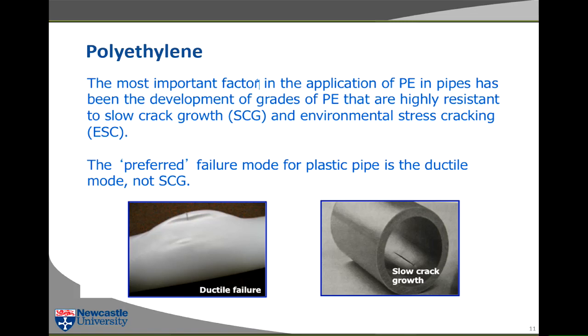When you do your fusion bond, butt fusion, remember you get a small bead here. That's just one wall of the pipe. So you push the two ends of the pipe together, you get a bead, and of course here you have a stress concentration from which a slow crack can grow. So that's what happened. Found this failure mode which nobody thought of, nobody had considered. So it stopped doing this and it started doing this.